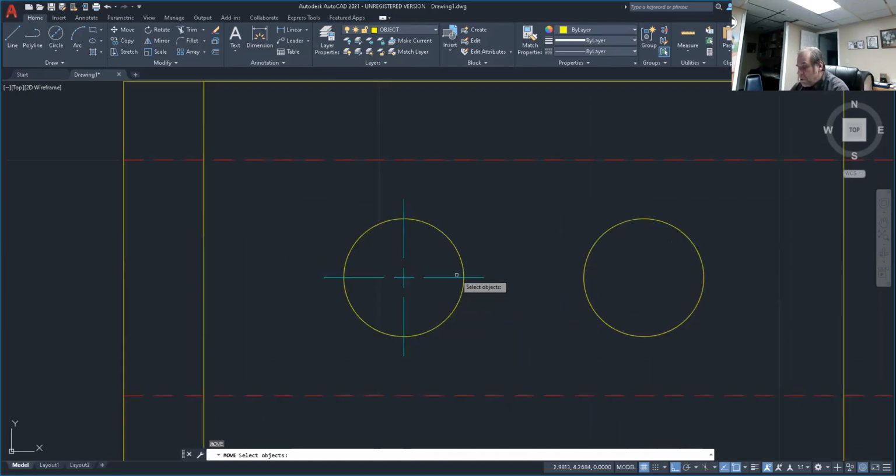Now, one more measurement you need to remember, and we'll review this quite a bit, so don't think you have to memorize it the first time around. A center line, if everything is right, in a perfect world, extends 1/4 of an inch beyond this circle. So these lines come out. Now remember, we just made it for a 1-inch diameter circle only. Any others, we might have to extend it or trim it back.